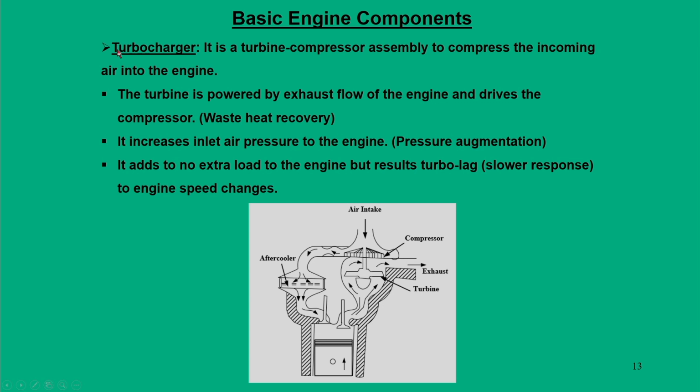The turbocharger also does the same thing, giving a pressure augmentation, or increasing the inlet air pressure of the engine, but through a different technology. That is called a turbine compressor assembly. Through this assembly it performs one important role, in a thermodynamic sense: waste heat recovery. From the engine exhaust, a lot of unwanted energy is still available, and we can use it with proper arrangements.